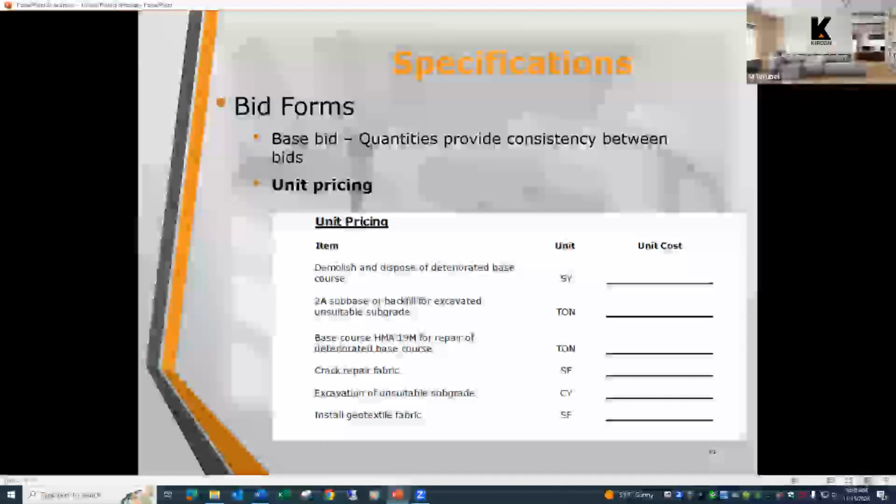Sometimes, as I mentioned before, if that mortar is deteriorated between the riser course, that's something that can be included as unit pricing, so that when the contractor comes through and removes the steel and takes a look at the inside of the basin, if they see that there is some block repair that needs to be done, that should be done prior to doing your pavement project.